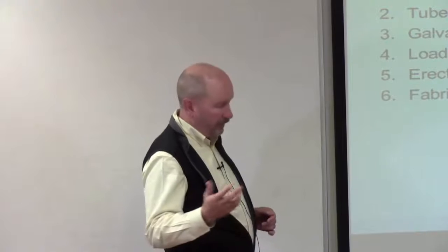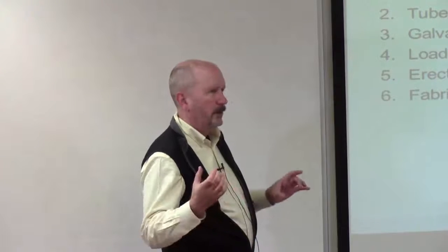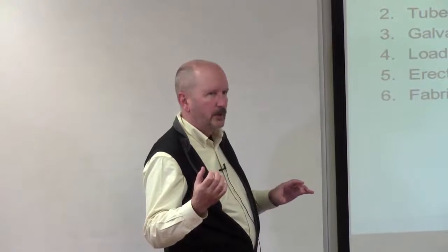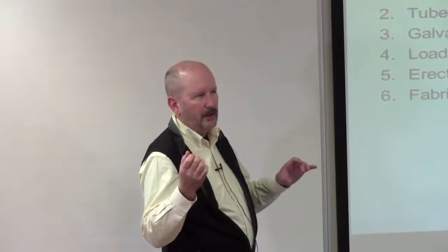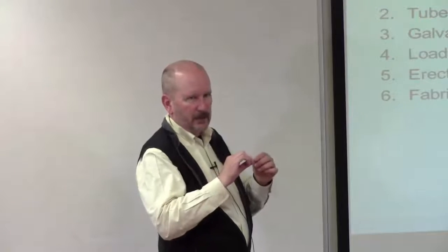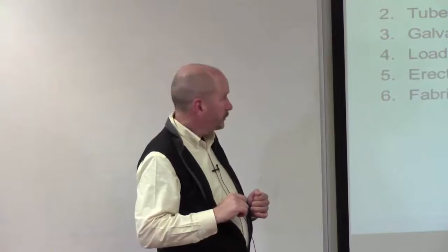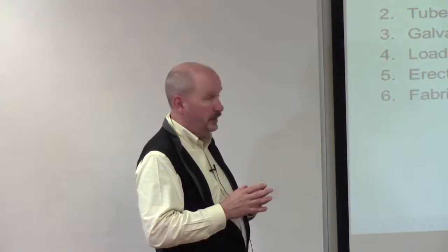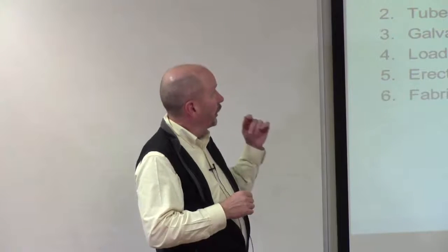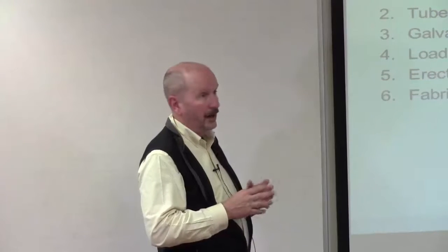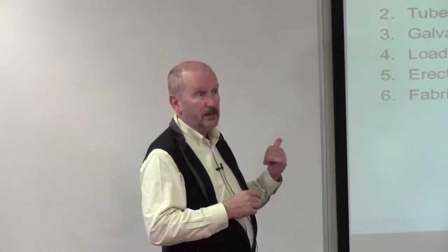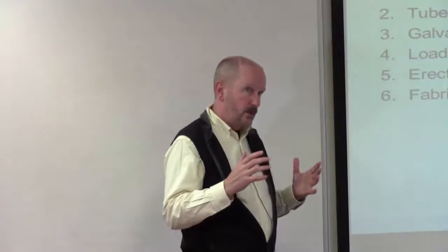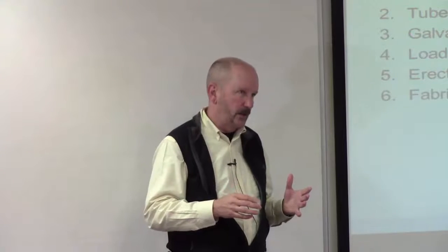But I think I've mentioned this before. One of our conductors is aluminum with steel reinforcement. When you're calculating the strength of that, you just ignore the aluminum. It's so small compared to the tiny few strands of steel. Really an amazing thing. We typically are going to encounter three types of steel in a substation: wide flange, tubes, and lattice. Now I'm not going to address lattice because it really isn't used that commonly in substations anymore.